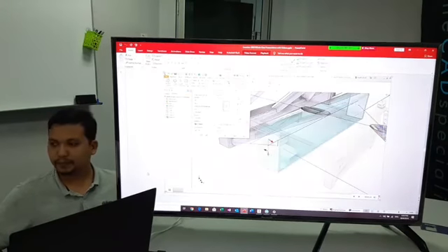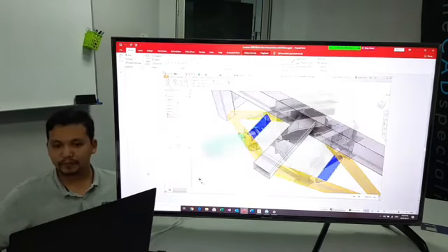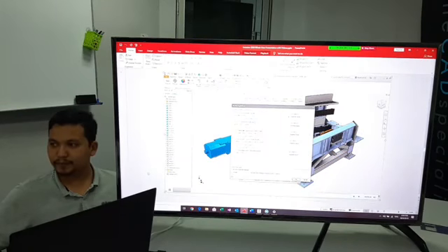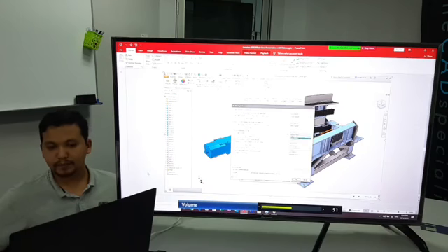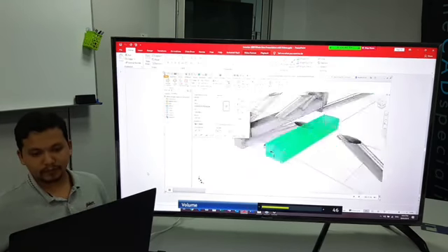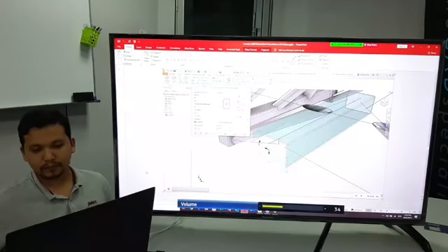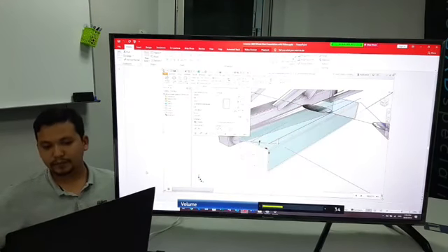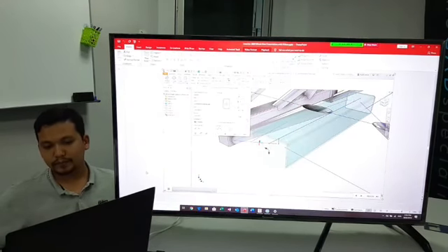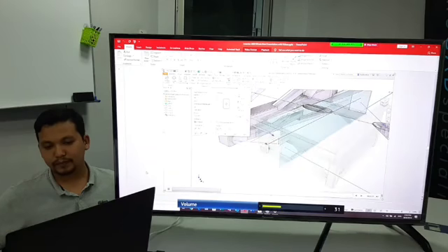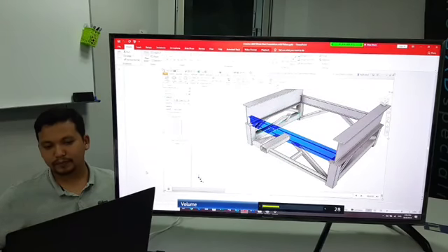Autodesk Inventor 2020 adds many user-requested enhancements to Frame Generator. Now, choose not only Frame Generator file name defaults, but you can also set the name for end caps in the defaults dialog. New in-canvas manipulators help you place, offset, and rotate your selection, making it easier than ever to visualize the orientation of frame members. Now find the multi-miter and multi-notch commands as a property panel.